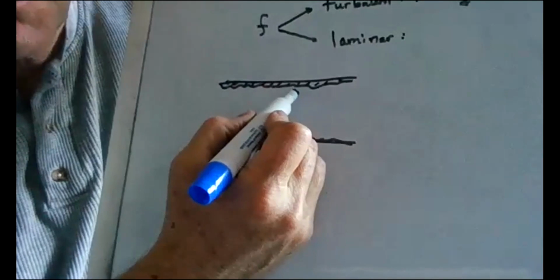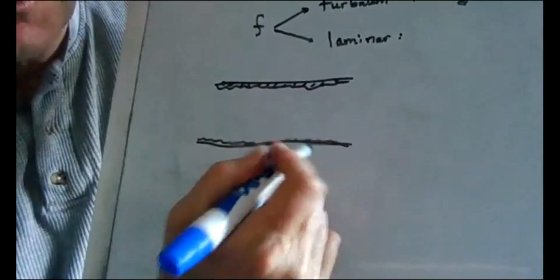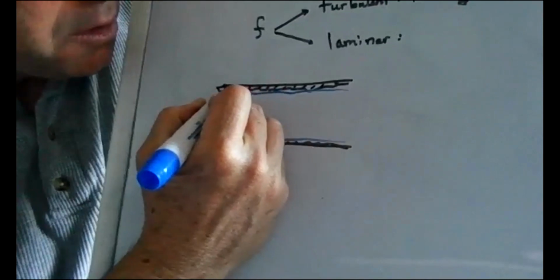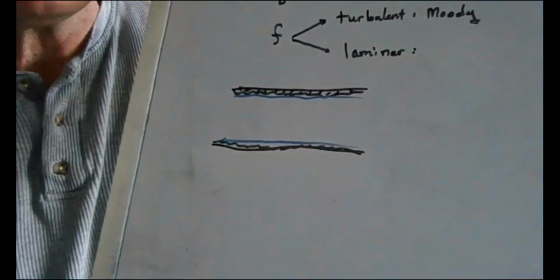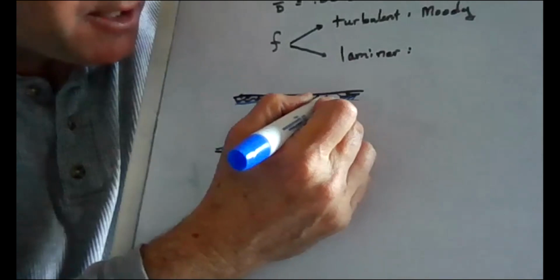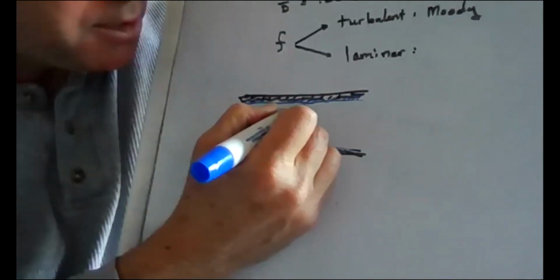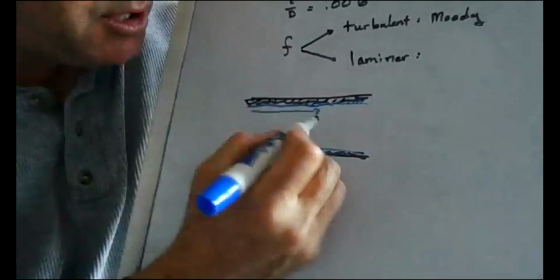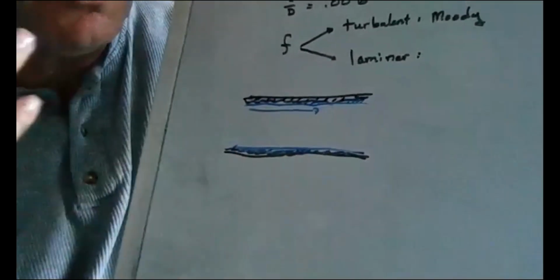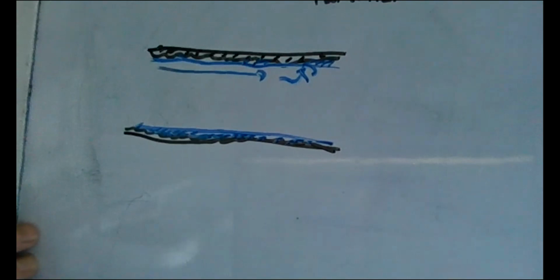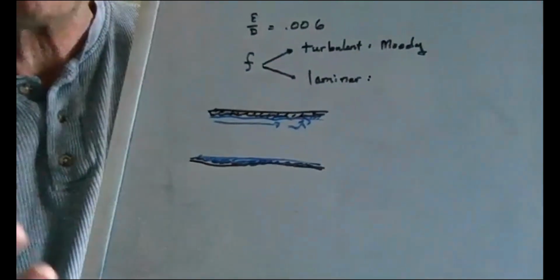The idea that I want to get across is that if it's laminar flow, roughness doesn't matter. A good way of thinking about it is, remember, there's a no-slip layer. That no-slip layer is down at the pipe walls. You can think of that no-slip layer as essentially making a smooth surface, because that fluid is just there filling in those little ups and downs, and it stays there. Does the fluid up here ever make a turn and actually come in contact with that wall? No, it's laminar. Turbulent flow, on the other hand, is swirling flow that has quite a bit of effect. We could get a swirl where it actually goes in there and ends up contacting that pipe surface. But if it's laminar flow, that roughness doesn't matter at all.